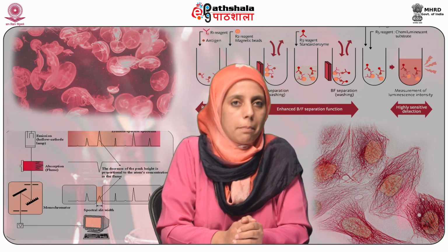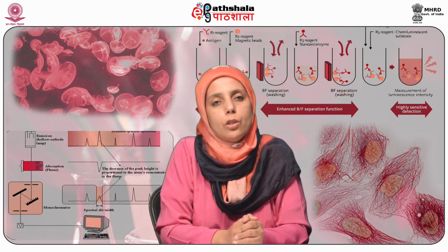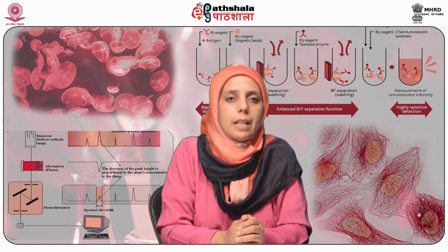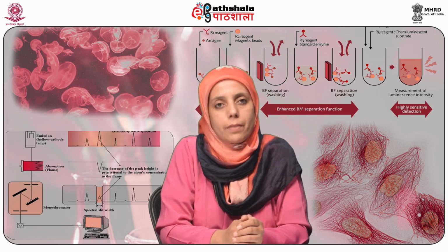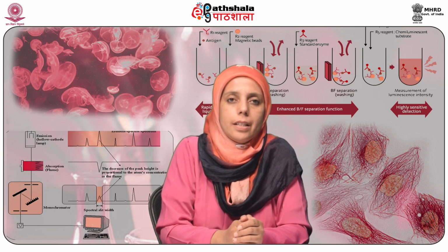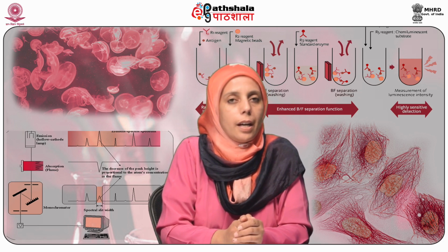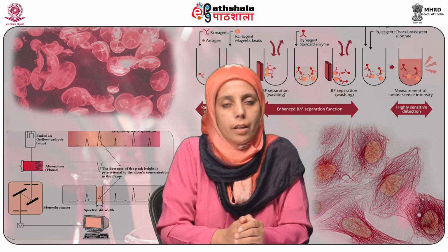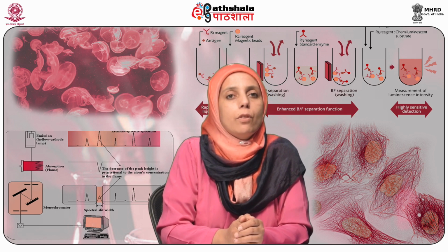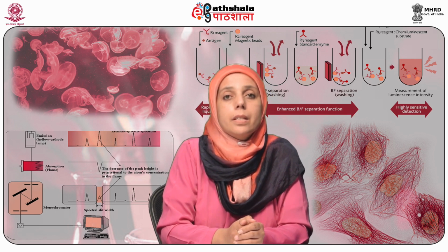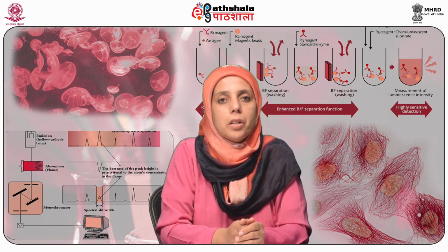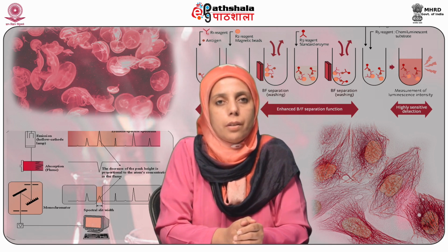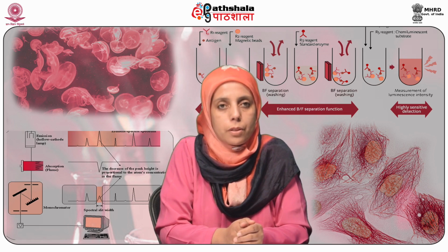First thing required is a sample, and you need to be very cautious while sampling because you cannot just sample at one place and say that yes, this is the amount of lead and water is polluted or not polluted. You need to have samples from locations that are representative of the water source, for example, storage facilities, treatment plants, distribution network, and points of use.